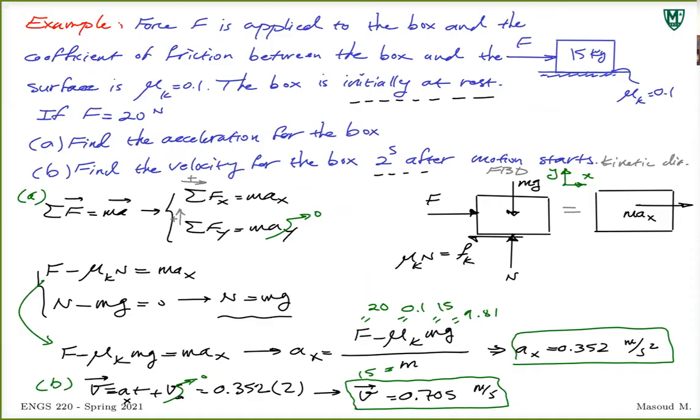And I told you there are 5 forces. Keep in mind when you're drawing the free body diagram, when you're isolating a part, think about these 5 forces: weight, contact, smooth contact or normal force, friction, force because of a spring, and force because of a rope or a chain or thread or whatever can only handle tension. These are the forces you studied in statics. And make it equal to the kinetic diagram, and the kinetic diagram again is just the acceleration, wherever the direction of your acceleration would be.